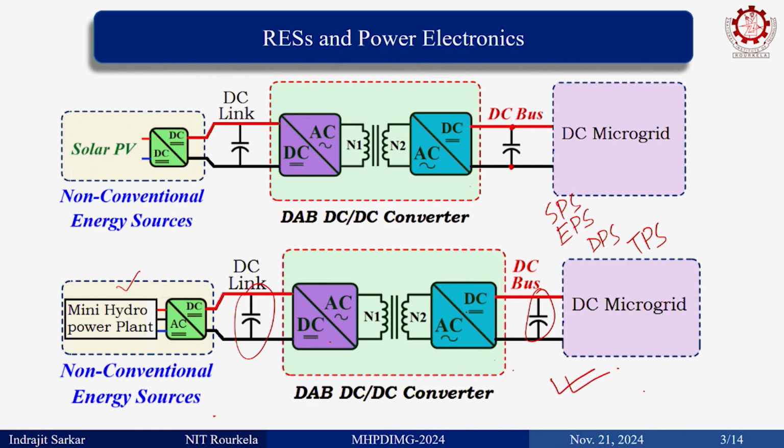The reference waveforms are given. You run the simulation and compare with the result that you obtain. You can play with the angles. It is in open loop mode. In closed loop, if it is, let us say, EPS modulation, then you have to control the duty ratio and the inner and outer phase shifts in order to control both the back power flow as well as the power flow from one side to the other. Participants will run these files and see the performance of the different modulation schemes.